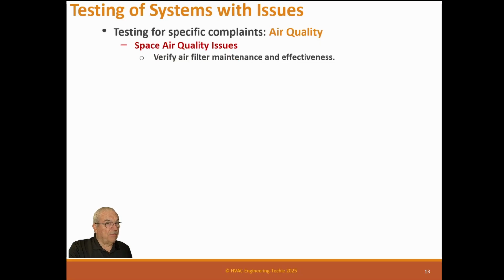But verify air filter maintenance and effectiveness. Is there any deferred maintenance as far as filters? Is the coil clean? Is the coil pan clean? Is there no green growies anywhere on any of this stuff? Because if you have a very dirty coil, then the dust alone could cause a problem. Or if you have growth on the coil or the pan, that growth produces spores, and the spores can go in the air, could affect a person, especially if a person's allergenic to those kind of things.